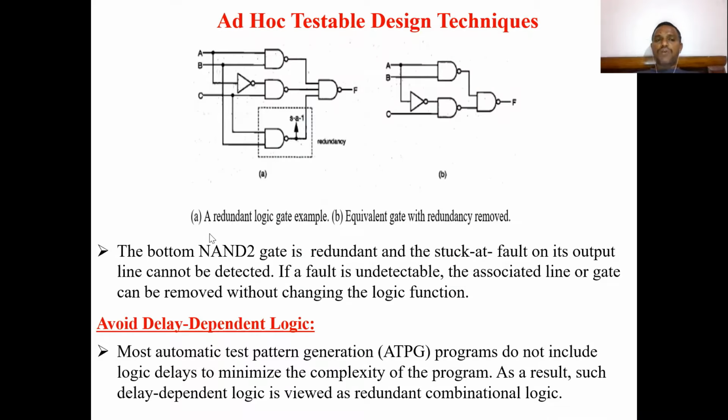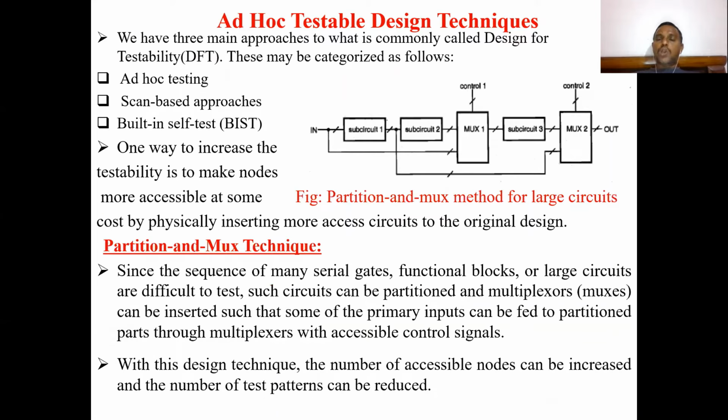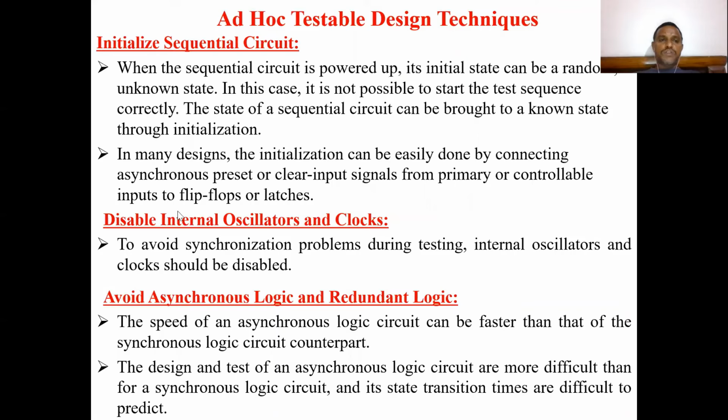These are the ad hoc testable design techniques we have. The first one is that we have to partition the large circuits and use multiplexers to apply the test vectors. Next one is to initialize the sequential circuits. We cannot predict the state of sequential circuits after power up, so to find the correct state, we have to initialize them with known values. Next one is to disable internal oscillators and clocks, to avoid synchronization problems.